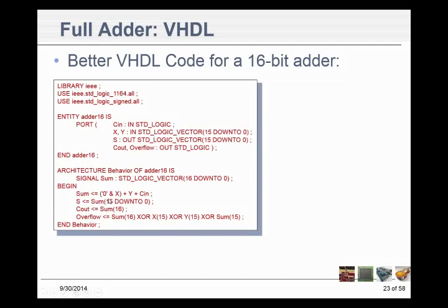And here, this is some strange syntax. That AND symbol is saying concatenate these two strings into one. And 0, because of its placement, is the most significant bit. Okay, so that 0 comes first, and then X, which is a 16-bit vector, comes right after that. So is the 0 going to be the carry? The 0 is going to end up being the carry out. What I'm doing is I don't want to have all these other bits floating around. I want to deal with them all in one place. So we've got that X with the extra 0 plus Y, which is a 16-bit number, plus a carry in. And if we have a carry out, that bit 0, this bit is going to change to a 1.